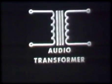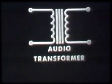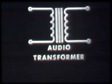Now, unlike a power transformer, which is designed to operate at a specific frequency, the audio transformer is designed to operate over the entire range of audio frequency, which is generally considered to be from 20 to 20,000 cycles per second. The schematic symbol for the audio transformer resembles that of the power transformer. The audio transformer, however, usually has only one secondary winding.